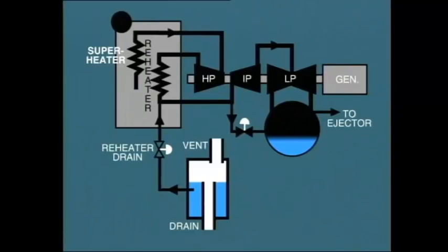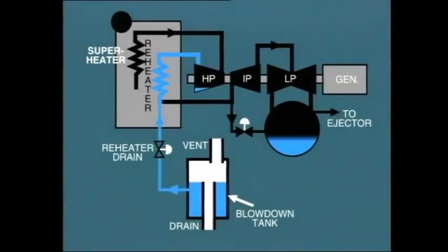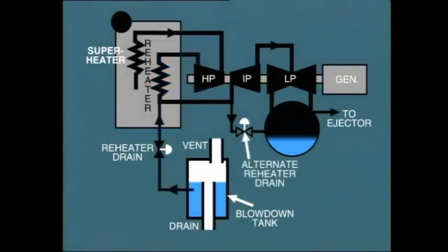In this arrangement, the reheater drains are piped to enter a blowdown tank below the water level. But remember, during startup, the reheater and associated pipework is under vacuum, forming part of the steam path through the turbine. You can see here potential for water from the blowdown tank being drawn backwards into the reheater and from here along into the turbine shell. To avoid this, the reheater drains would normally be connected to the condenser during the startup period. The connection to the blowdown tank would only be used to drain the horizontal reheater before lighting the boiler.